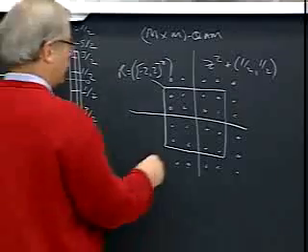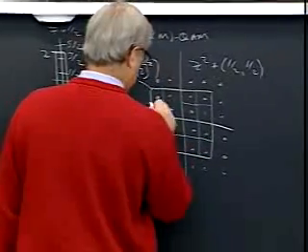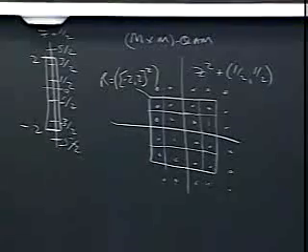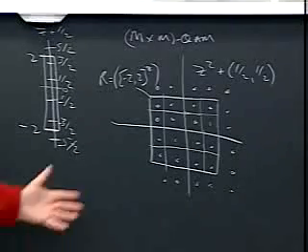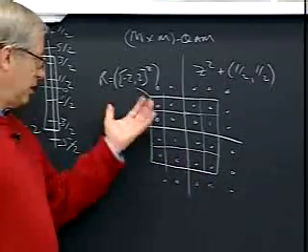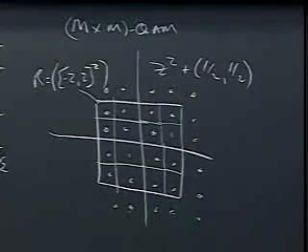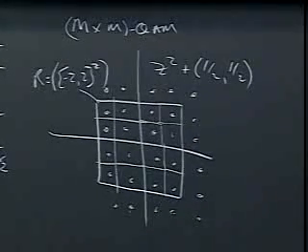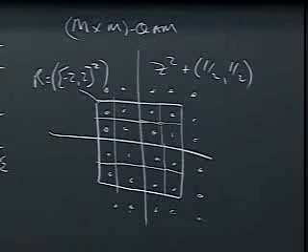Each of these, you might think of as just taking the little square around each point. Each of these squares has area 1. So when we take the union of all those squares, we get the region. That's another way of characterizing this region: it's just the union of all the decision regions of the points that we want. If you started from the points, you could certainly invent a region that is the union of those decision regions. It would have an area equal to the number of points times the volume of 2-space per each point. That's the kind of approximation we're going to use. The bounding region is clearly going to have something like the number of points in the constellation times the fundamental volume as its volume.